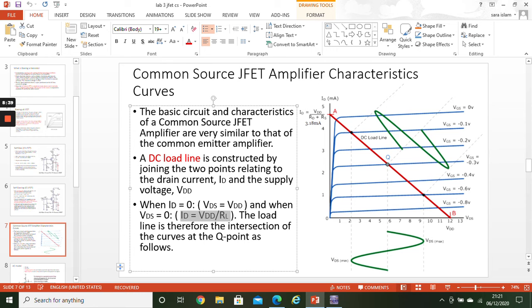Now you know that the load line is drawn by joining these two points. Also you are familiar with the concept that this whole area is the linear behavior of your transistor. It means other than the value of VDS approximately 1.5, so a value greater than 1.5 and approximately up to 12, somewhere in this region, whenever you are applying any millivolt AC signal, you can amplify it.